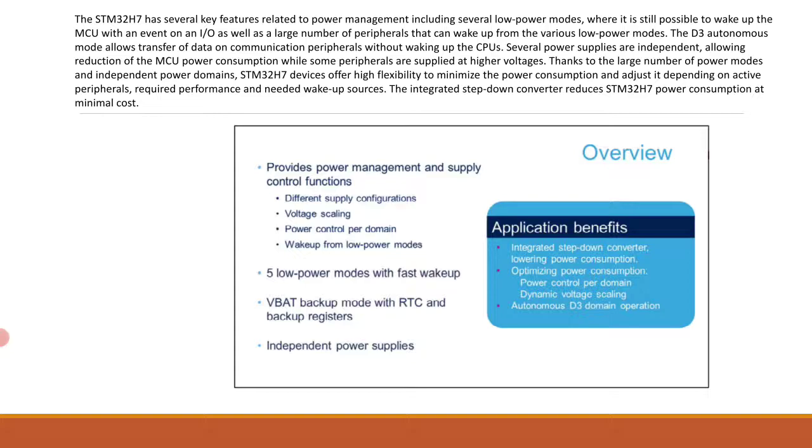Thanks to the large number of power modes and independent power domains, STM32H7 devices offer high flexibility to minimize the power consumption and adjust it depending on active peripherals, required performance, and needed wake-up sources. The integrated step-down converter reduces STM32H7 power consumption at minimal cost.